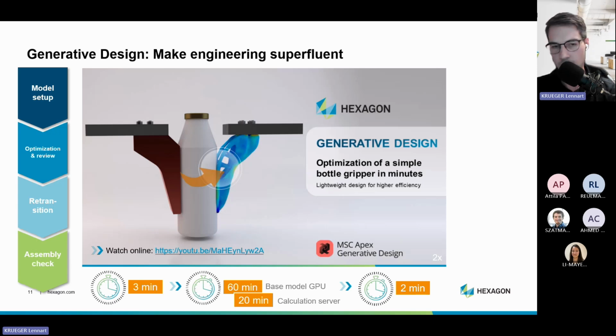We start with a real coarse resolution, and then over time, the resolution gets finer and finer. At the end, we have a final design, a suitable design, which can be more or less directly used, at least for additive manufacturing. So no disconnected struts, no unclear structures. And with one click, we can go back to a CAD file, this step right here. We also automatically attach back the boundary conditions, and then we can easily switch to Apex for Nastran.